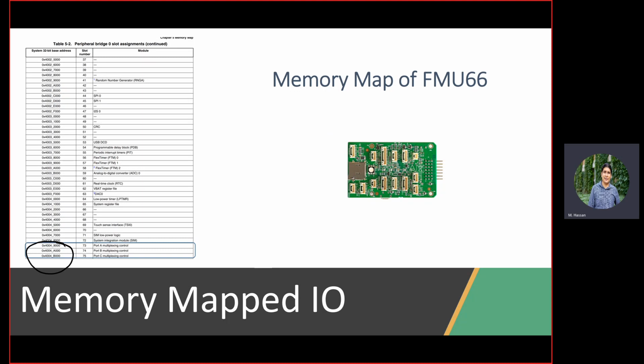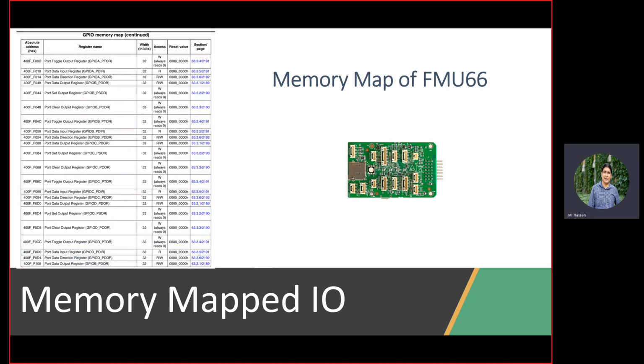So if you write a driver, if you are like an embedded software engineer, which is what you have done in Lab 0 for the LEDs, then you need to know where these addresses are and you need to write your driver in a way to write into them and interact with them. Good. And then basically every port has a memory portion. The first address is the address of that port, but then inside the port, there are multiple registers. As we said, there are status registers, control registers or configuration registers, there are read registers and write registers, right? So another table, which is the GPIO memory map table, gives you the specifics or the details of how you can interact with this port and what the addresses of the registers you want to write to are.